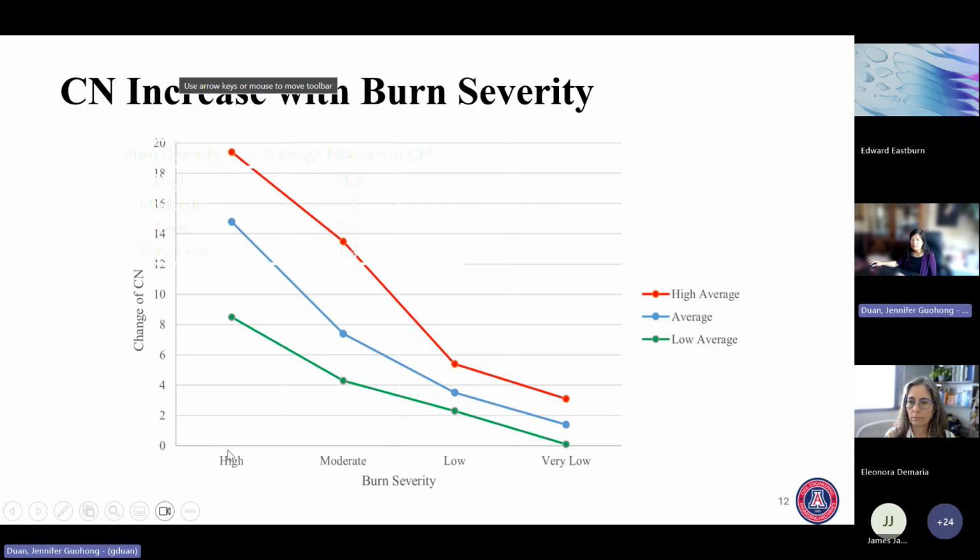Okay. So if this is high burn severity, you can use the maximum curve number increase of 19, or the minimum reduction, from what we see from the Catalina Mountain, of about 8.4. Or you say I use an average, and how much risk you want to take.